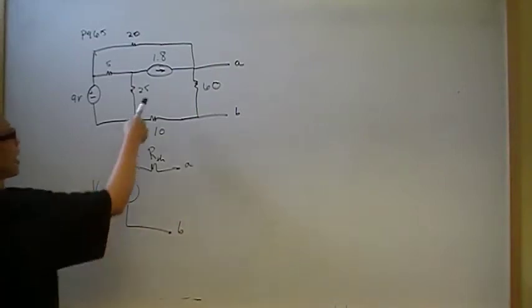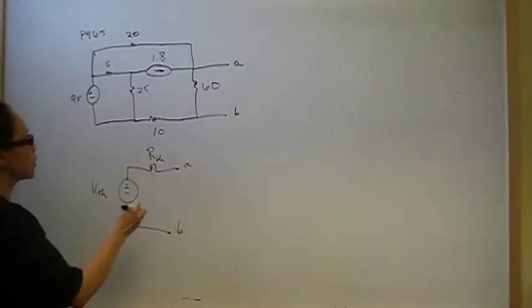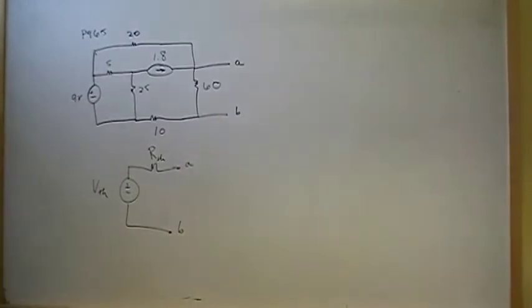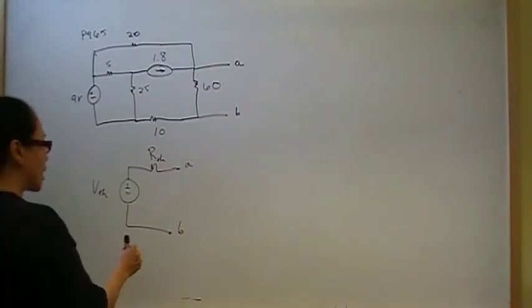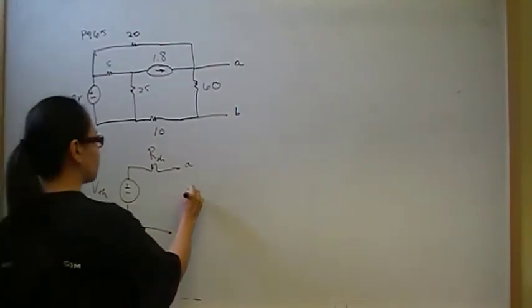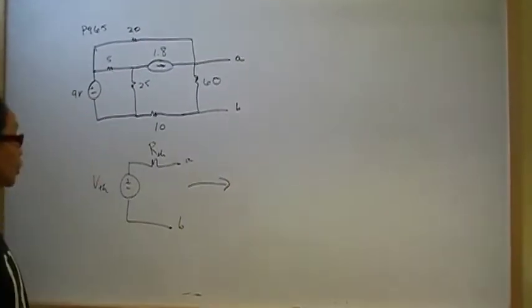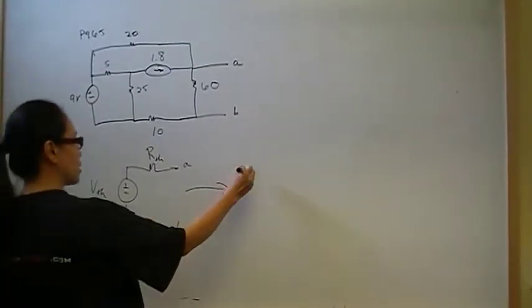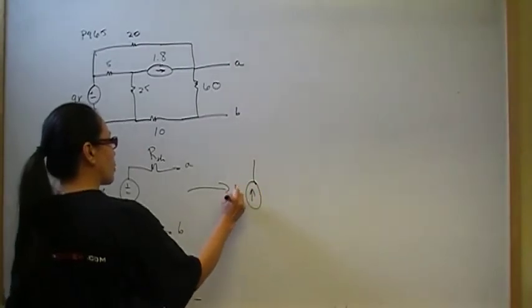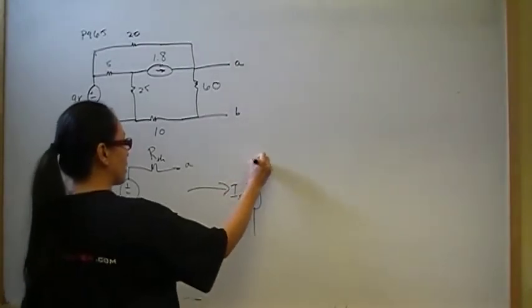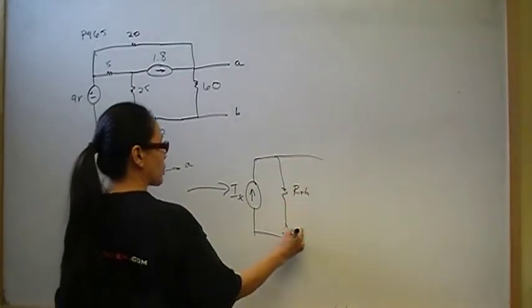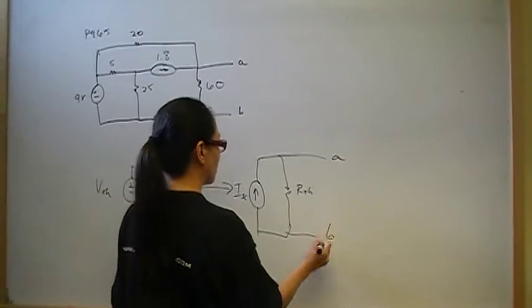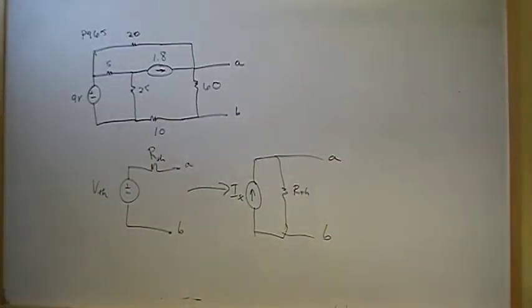because we don't always really care about what's going on inside a circuit. Sometimes we just care about what's happening at the wall outlet, or some point of view, and what is happening in there is not something that we care about. So that's a Thevenin equivalent circuit, and to find its Norton equivalent we just do a source transformation. If we wanted to express it in terms of a current source, we could do that with simply a source transformation.